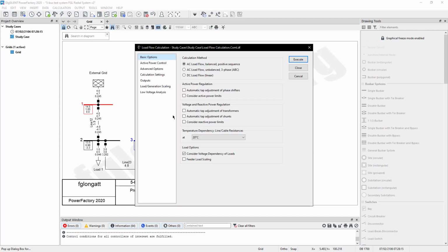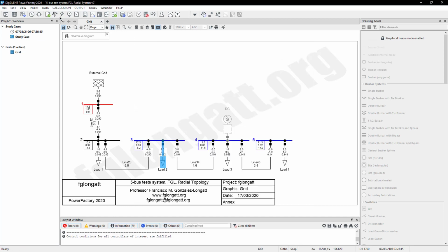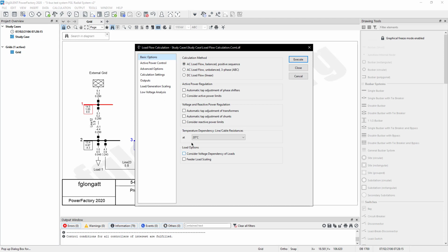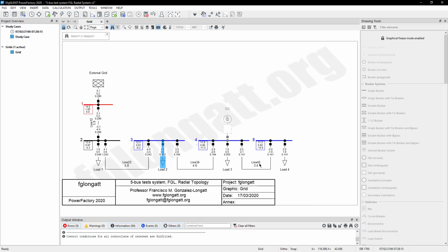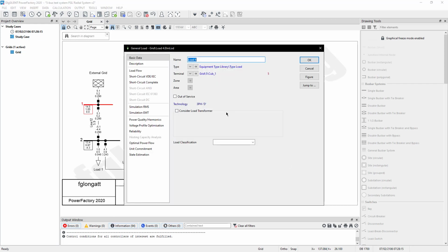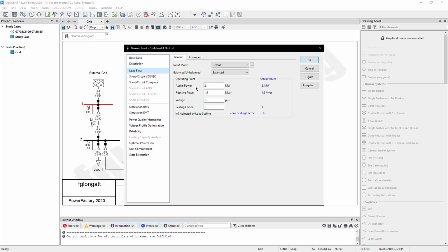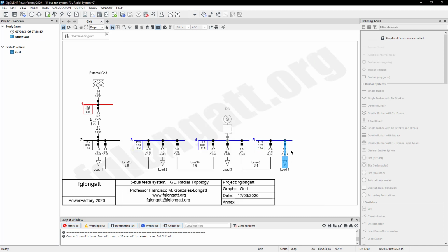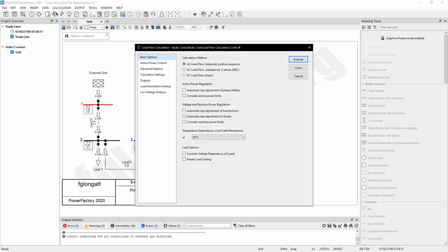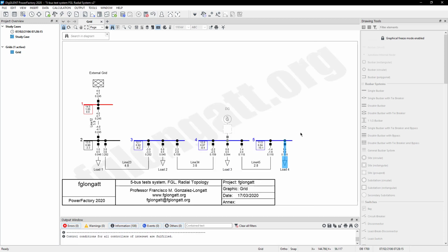What I will do now is again disable the voltage dependence, run the classical load flow without considering the dependency of the loads, and let me focus here at the tail. At the tail we have 0.82, it is a very poor distribution feeder, and this load is 2 megawatts, and that is the nominal power of this load, okay? However, when we include the voltage dependence, what is the surprise? Wow. The surprise first is the actual power consumption here is 1.4 megawatts.